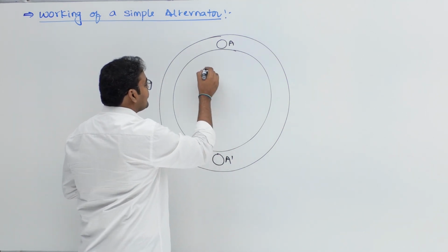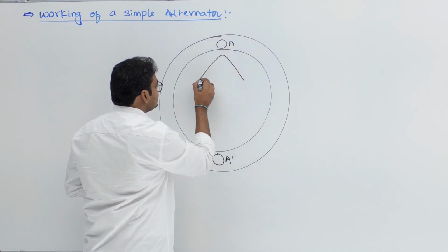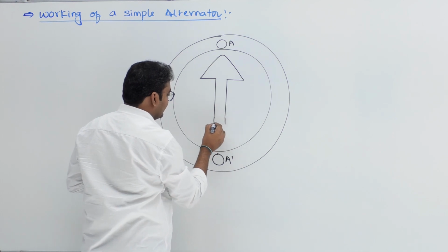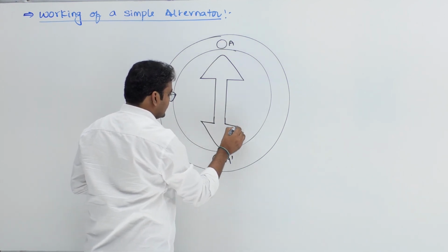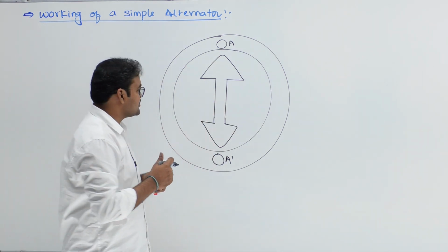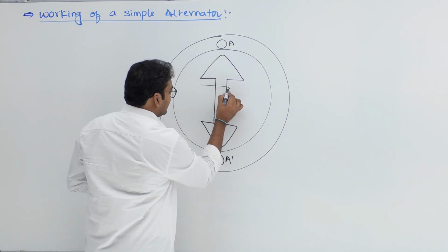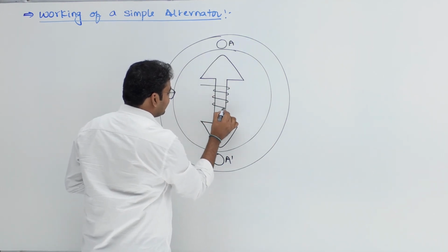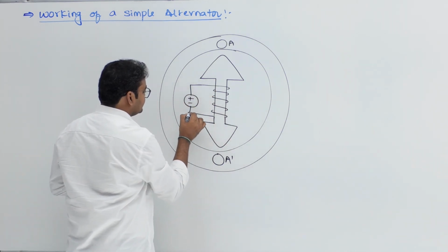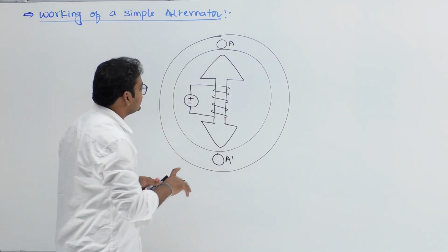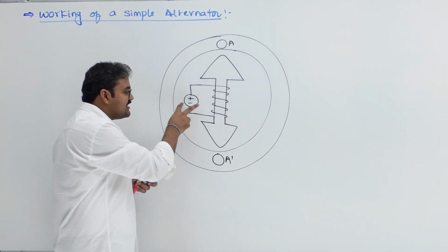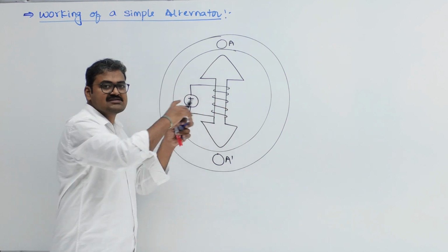Now inside this machine there is a rotor magnetic circuit. Assume there is a simple rotor magnetic circuit like this. And I told you we are using DC field excitation. Therefore assume this is the rotor and this is the rotor winding. You see, a number of turns are there, and this rotor winding is connected to a DC supply. You may have a doubt here: the rotor is rotating, yes or not, but this DC supply is given from outside. Externally we will give the DC supply.